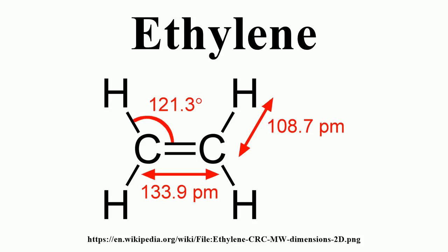In a related process used in oil refineries, high molecular weight hydrocarbons are cracked over zeolite catalysts. Heavier feedstocks, such as naphtha and gas oils, require at least 2 quench towers downstream of the cracking furnaces to recirculate pyrolysis-derived gasoline in process water. When cracking a mixture of ethane and propane, only 1 water quench tower is required.